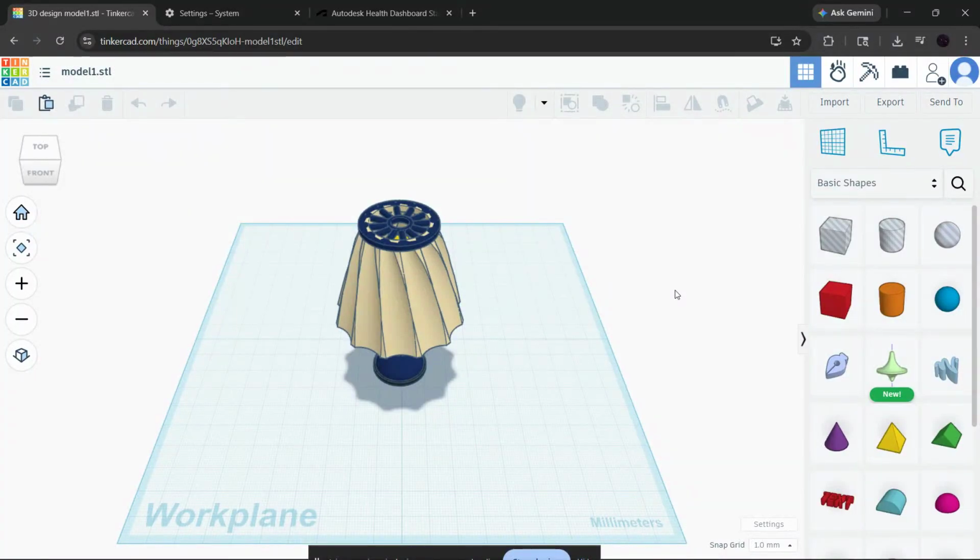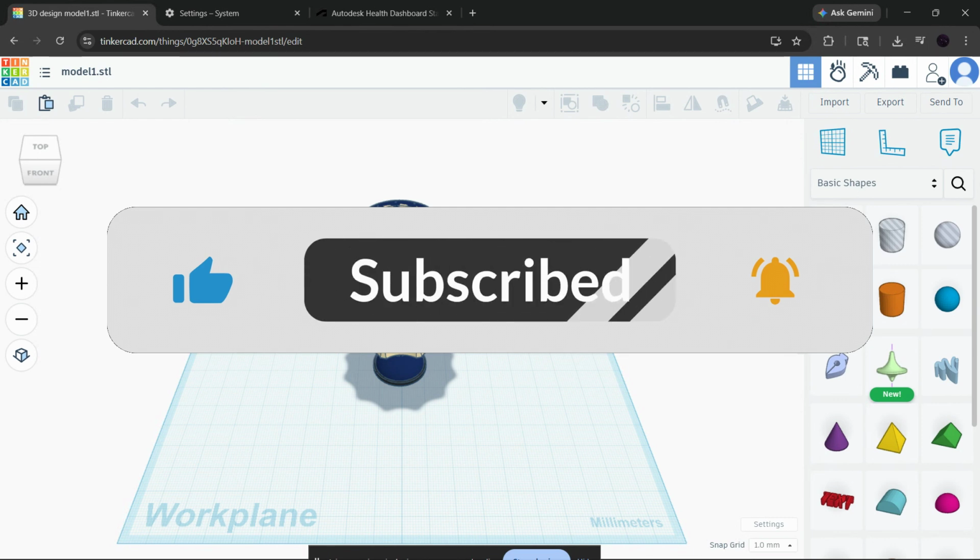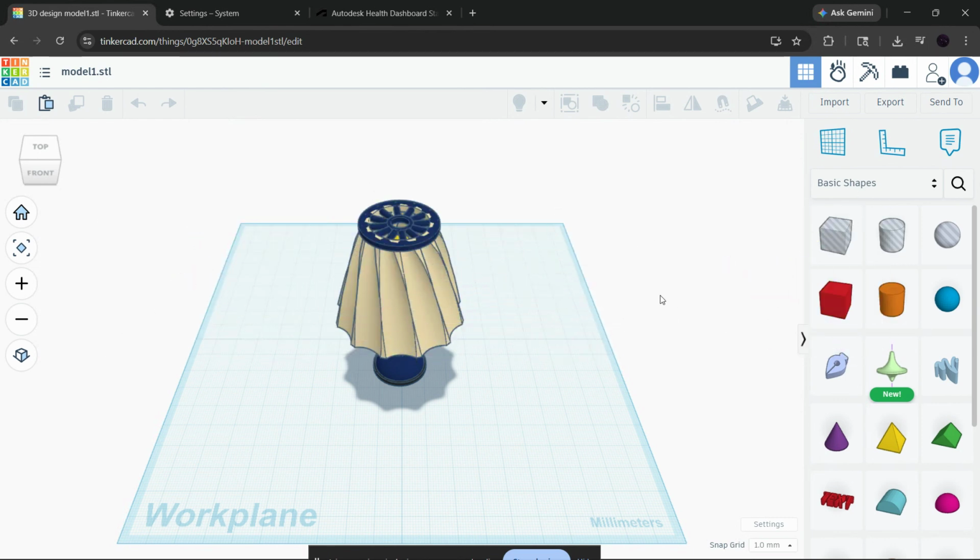If Tinkercad is showing the error "something went wrong," don't worry, because in this video, I'm going to walk you through the fastest fixes step by step so you can get back to designing without the frustration. This error can happen for a few different reasons, including browser cache issues, extensions like ad blockers or VPNs, graphics settings, broken project geometry, network problems, or even circuit simulation errors. The good news is that most of the time, you can fix it in just a few minutes.